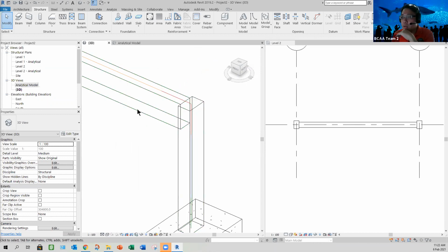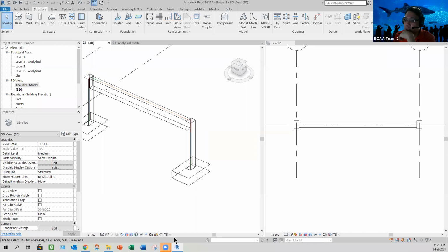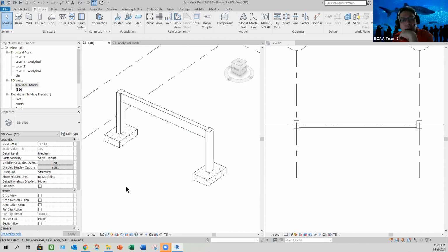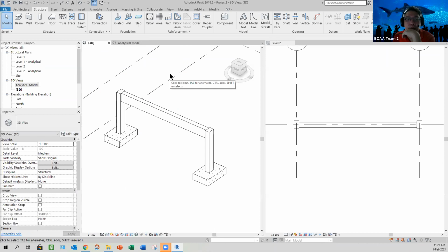You see now, this is what they want, not your model. The analytical line is the concern. But because you are doing only a structural model, we don't display this. And the view should be default hidden line, because you're seeing the model. That's why you can see structure has two, calculation and model. Okay, all good.